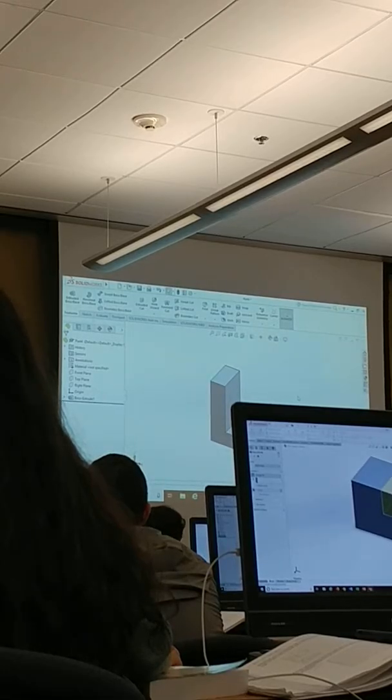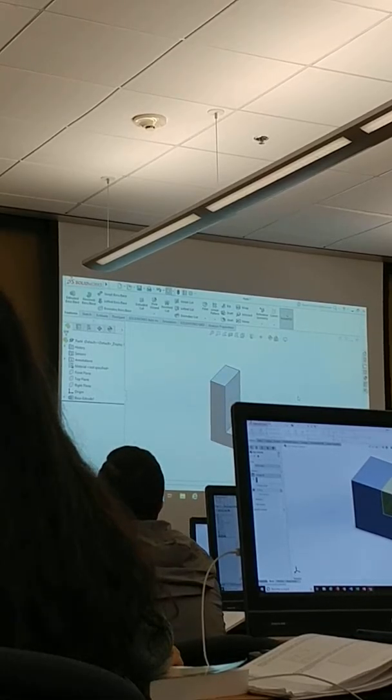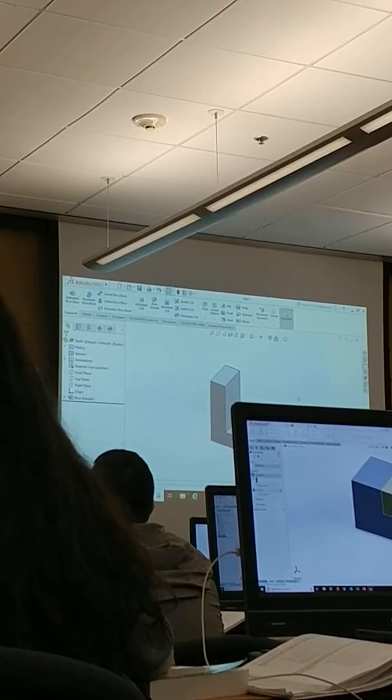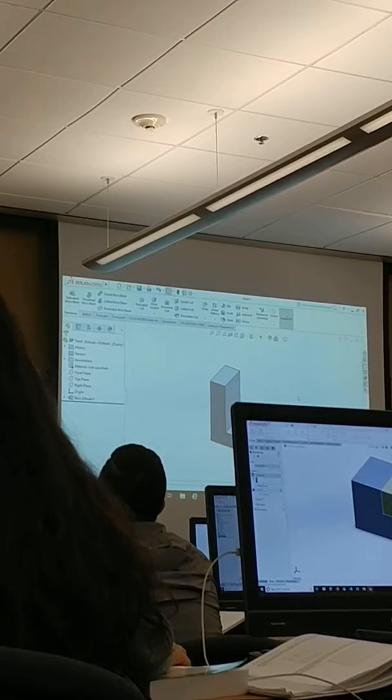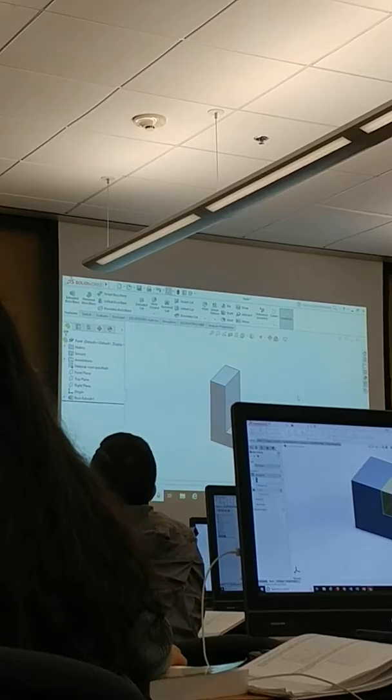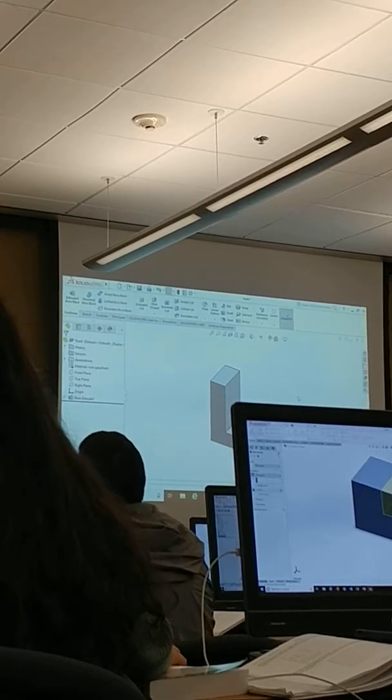But there's times where I've made a part that was a 1/4 inch by 1/4 inch, and the sheet metal shop had like a 30-ton press brake, whatever, and they just bent it. Like, oh, we can make this out of 1 piece, and it'll be half the price. Are you okay with a little radius if we bend it? Yeah, sure, I don't care. Go back and change my drawing, and then I'll do that.